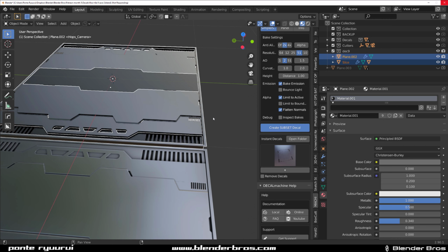This pulling is, like I said, caused by overhang geo, so the geometry is not boolean together, it's simply Ctrl J joined, but it's not actually one piece of manifold geometry, which causes problems. So I could technically run a boolean over there, and maybe this would fix the issue. I might actually do that one. So if it's not gonna be okay now, we're gonna run union boolean on these two, and this should fix the issue. I had no problems with previous ones, but this one's causing issues, so what are you gonna do?